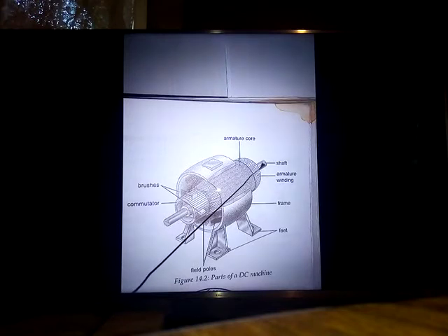And on this armature there is a shaft. The purpose of the shaft is to suspend the armature onto the housing, the frame of the machine, so that it can rotate freely. Okay, so we've got the casing, which is the yoke, and the yoke is made out of cast iron or wrought steel, or as I mentioned earlier on, an alloy of a little carbon and steel. It is a ferromagnetic material, right?